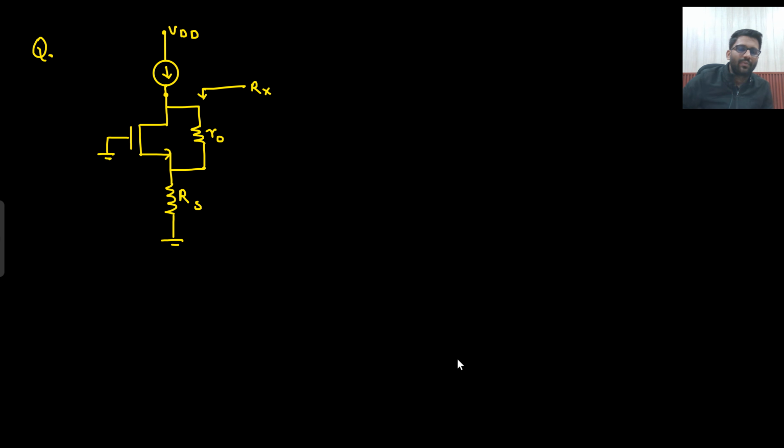You need to find Rx from here. Try doing it. This is also a very good circuit, very standard circuit. Okay. So try finding Rx. What you will do? This current source, this will be gone. VDD will also be gone. Okay. So what will be your final circuit? So final circuit will be something like this.